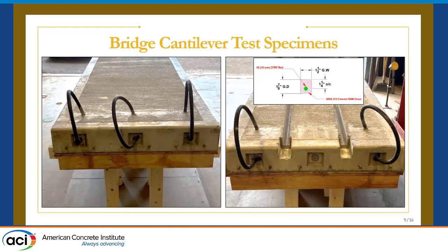And then what we're proposing is putting in the CFRP bars through the NSM rehabilitation method, or near surface mounted. So to show you a drawing or schematic of that: in terms of the dimensions of this NSM groove, because it's a cantilever, it's negative moment, so your tension side's on the top. So you'd put it on the top side where you would cut your grooves.